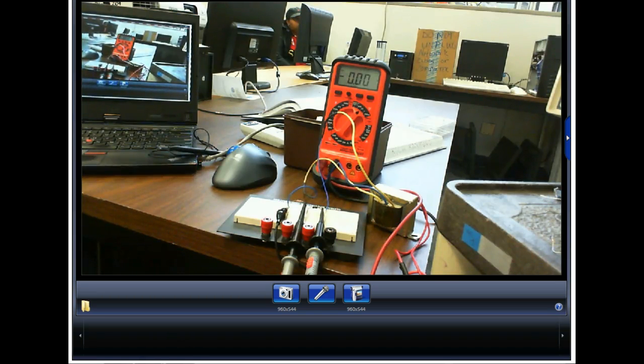And why we really make sure you understand that is because this has gotten people hurt. They go up there and measure a circuit they think doesn't have power on it, they measure 0, and then they stick their hand in there. And they had their meter on what? They had the meter on DC when they were measuring AC. Now luckily, if you have it on AC, it's going to show you something, but it's going to be wrong. But if you have your meter on DC and you're measuring AC, it's going to show you 0, unless there's some garbage out there.